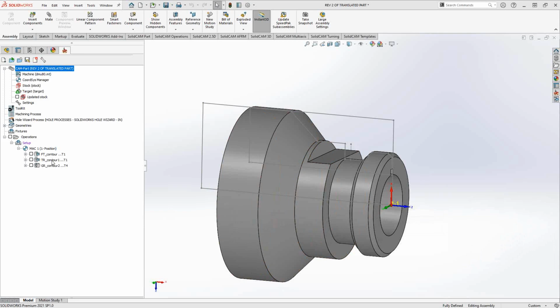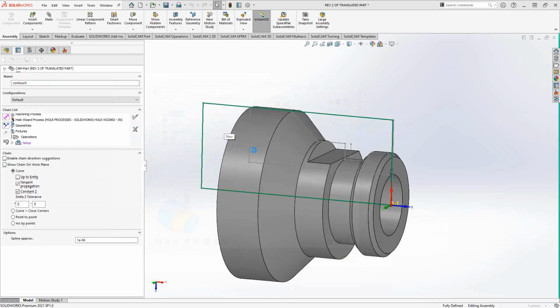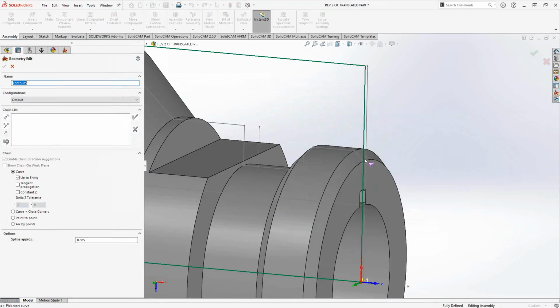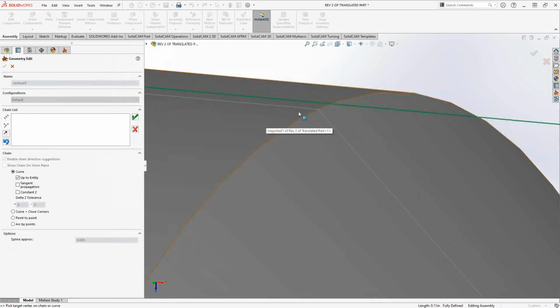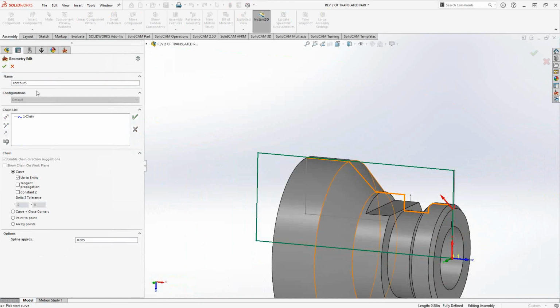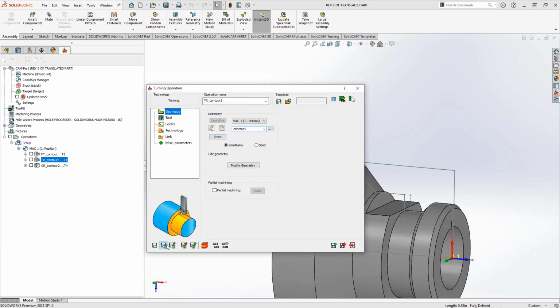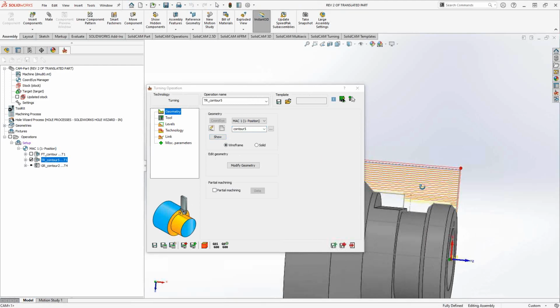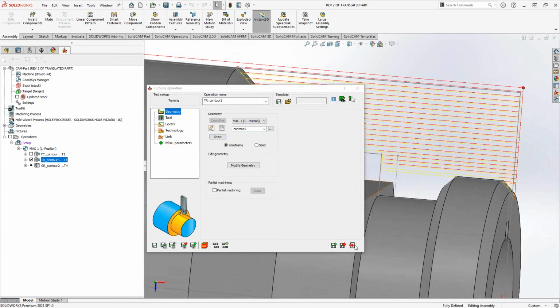So what that allows me to do now is go into any toolpath that needs to be updated. In this case, this guy here. So it's not associative, but I kept my toolpaths, I kept my tool table, all my design, all my programming functionality is still there. I'm just going to reselect that geometry, and then I should be able to just recalculate. You can see now that it turns it to the new groove, the new width of that new groove.